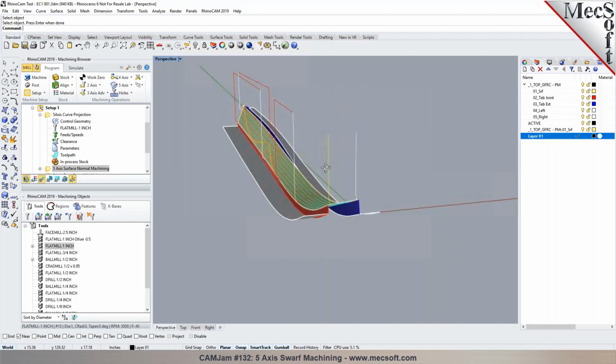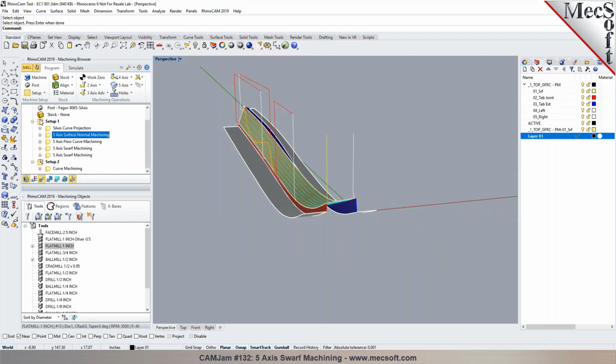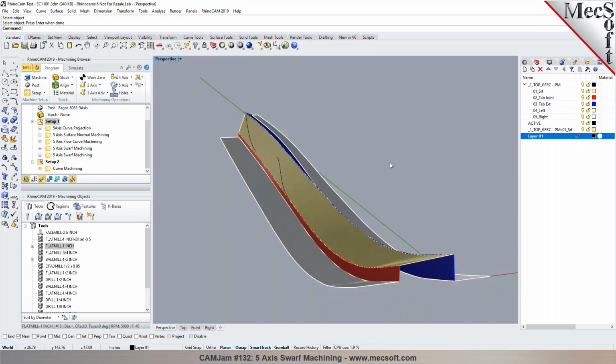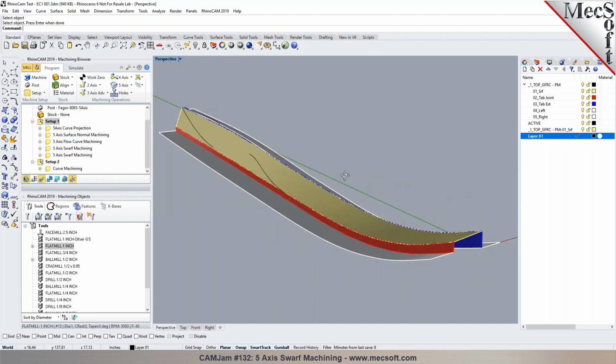Interesting. I got a question. So is there, maybe in the 3-axis, something similar to flow line, 5-axis, but an operation that would follow sort of the ISO curves of the surface? Yeah, but we can do what is called a between curve machining. So let me show that to you here.